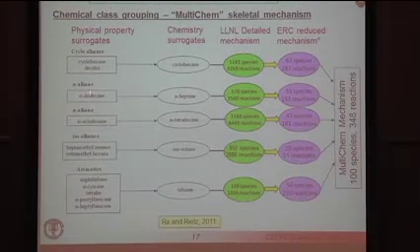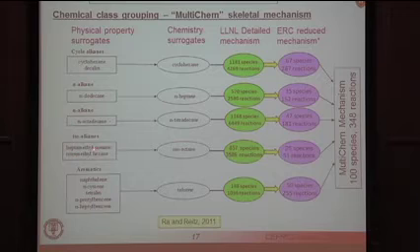Similarly, for, say, the isoalkanes, we represent them with isooctane. We take the isooctane mechanism of Lawrence Livermore and reduce it to a 25 species mechanism. Aromatics we represent with toluene, same type of thing, and ultimately create a mechanism that consists of roughly 100 species and can cover a wide class of fuel types.